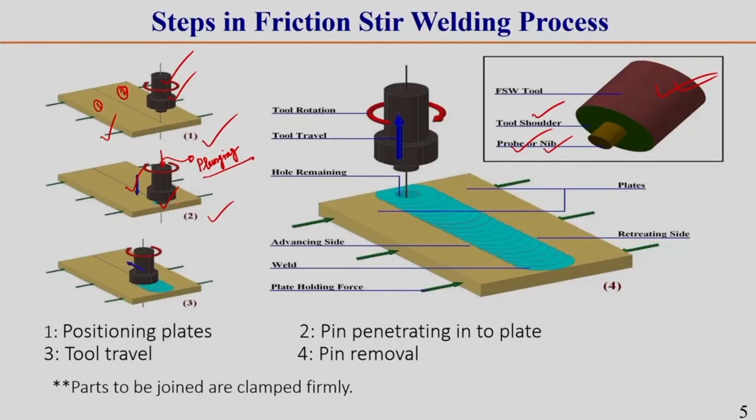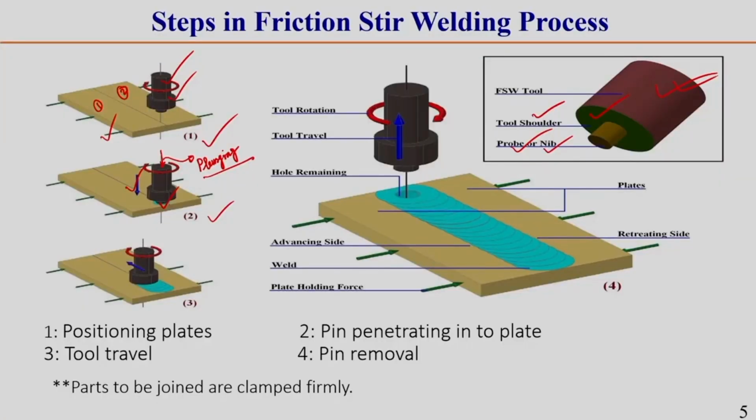So, what happens once the material becomes soft enough, at that time we use a downward motion. During the downward motion the tool gradually penetrates the thickness of the workpiece, until the tool shoulder surface contacts the workpiece surface. So, from touching of the workpiece with the tool pin tip to touching of the shoulder surface with the workpiece surface, this time is called plunging time.